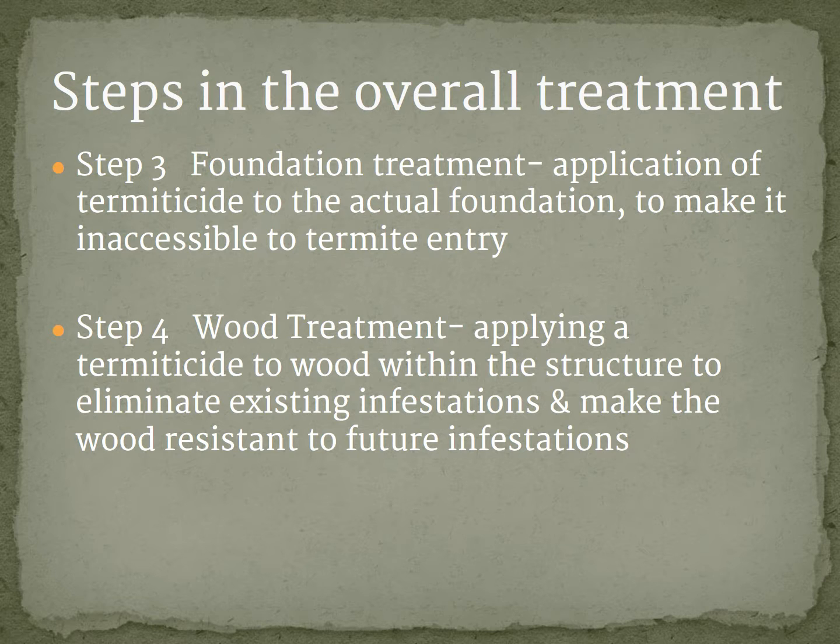Another type of wood treatment can be with a borate, and especially when you're dealing with drywood termites, a lot of times you'll see the little kick-out holes in the wall and the pellets. Then you'll drill into those and use a borate type of product like a Timbor or a Boracare. This type of product will go right up into the galleries of the drywood termites and actually shut them down.